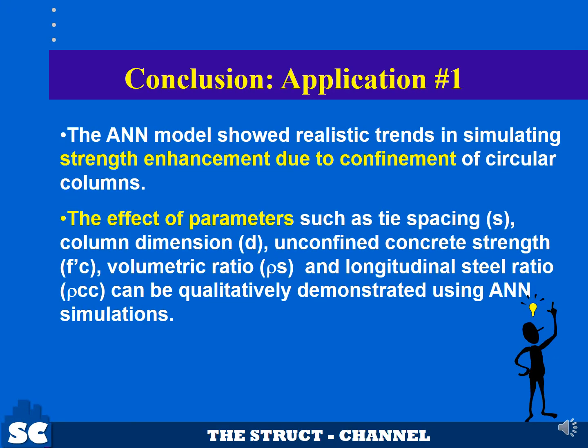Conclusion for application number 1. The ANN model showed realistic trends in simulating the strength enhancement due to confinement of circular columns. The effect of parameters such as tie spacing, column dimension, unconfined concrete strength, volumetric ratio, and longitudinal steel ratio can be qualitatively demonstrated using ANN simulations.